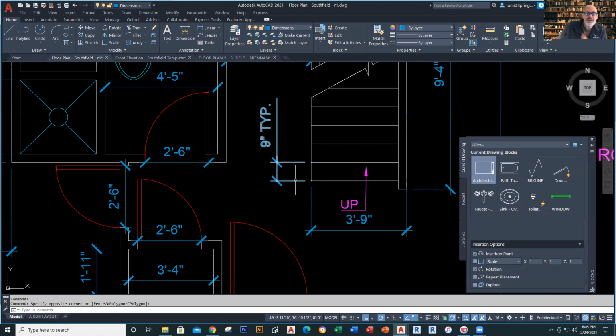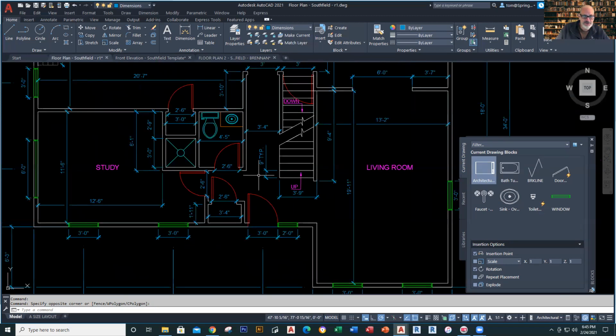Okay, so, well, let me just tell you this right now. Remember this. The secret of stairs is 7-11. Typically what that means is the actual rise, the portion of the stair that actually goes up. There's the tread and there's the riser. The riser is typically 7 inches in residential construction. And the tread, where your foot actually sits, is typically 11. So it's 7-11. Now, it can fudge a little bit one way or the other, but typically 7-11 is the most common dimensions right there.